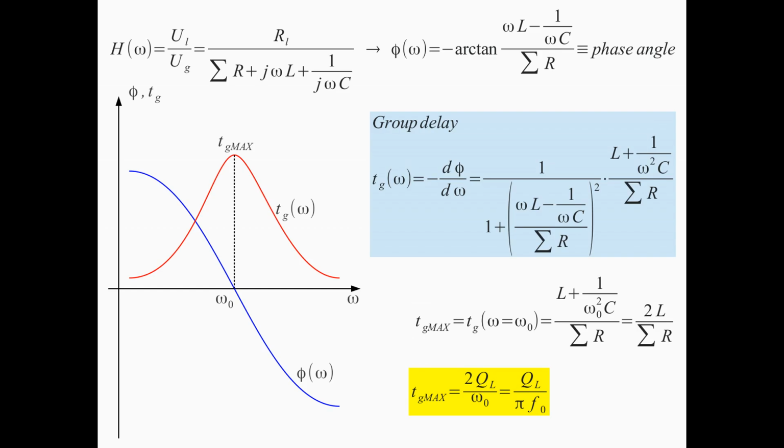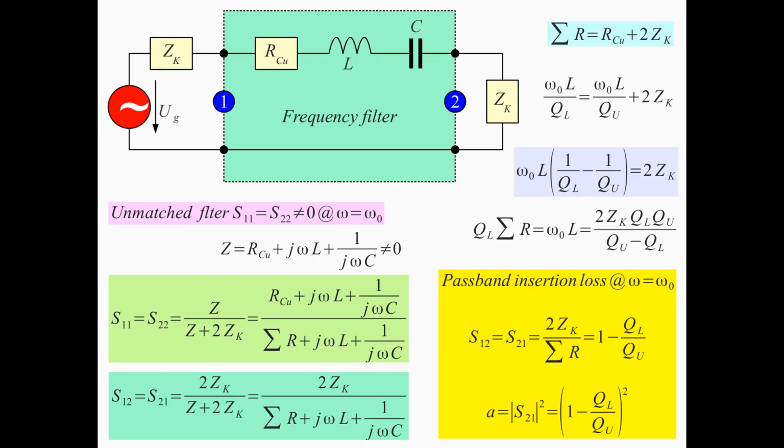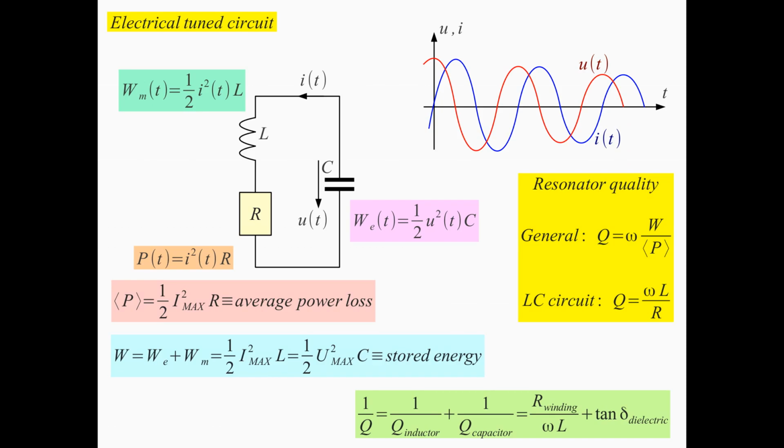Finally, talking about filters, we have to understand that filters also have a group delay. Where the group delay comes from: if I have a tuned circuit, you see that this tuned circuit is ringing after the oscillation is started. This is still ringing for some time before the oscillation vanishes. This ringing introduces group delay to my signals.